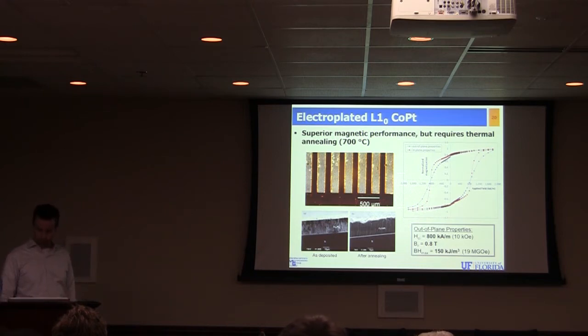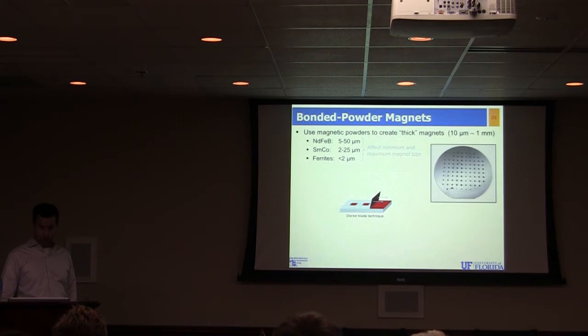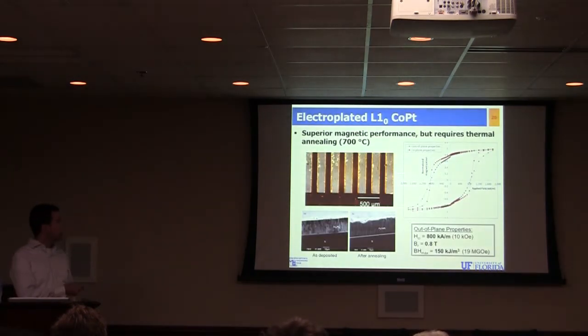Cool. Thank you. So you will heat them, annealing above Curie temperature, yes? Yeah, so in this one we cycle it at 700 for a 40-minute anneal, and then when we cool it back down, you actually induce a phase transformation in the crystal lattice, and then they exhibit the positive curve. It's a very narrow hysteresis curve. It's almost like a soft magnet. It's done in the presence of a magnetic field.